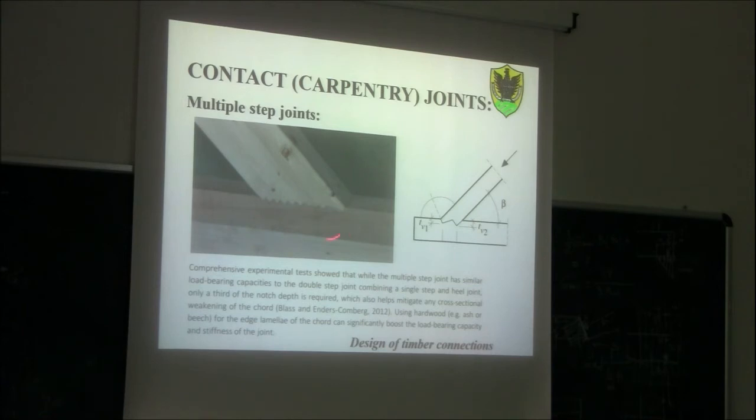No. This one was to get much better results compared to the normal one. And the other comment was that this hardwood here is usually only one lamella. Now in this case it's a very thick lamella, but if it was a normal 4 cm lamella, it would be cut with only one step, because the one step is much deeper here. So it would cut the lamella completely, whereas with multiple steps, it doesn't cut the lamella because they are more numerous and shallower than the other one.